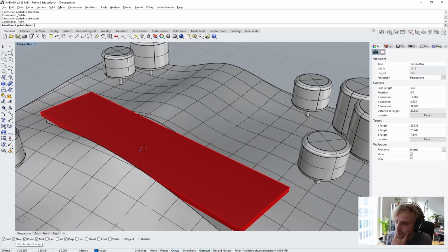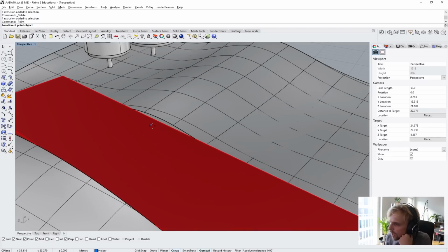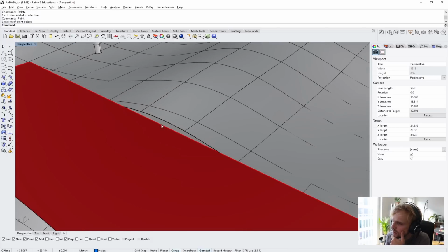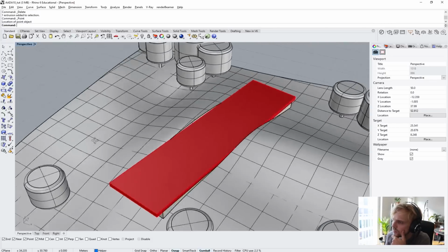So nearest snap is turned on so that you can snap to an edge of the box. And wherever I want to have an entrance or exit of the pavilion, I'll just put a point so that I don't forget, right? So I guess there can be the entrance.